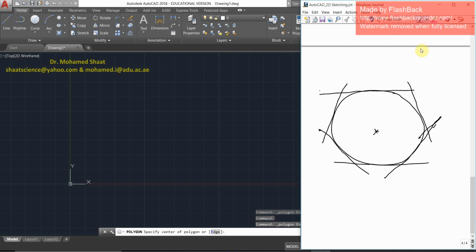There is another option. It means that we already set up a hexagonal shape with 6 sides, all of them tangent to the circle. Make sense? There is another option where we can set up a hexagonal shape, but instead of using sides that are tangent to the circle, we're going to use sides that intersect with the circle. This is the first side, this is going to be the second side, the third side, the fourth side, and the fifth and the sixth side.